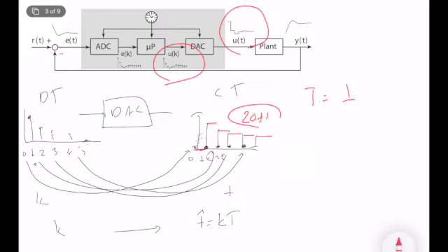Applying zero order hold is cheap and easy, and instead of putting your effort into implementing first order hold or other kinds of hold operators, you just try to increase your sampling rate, which is much better than approximating this function a little bit better to reflect the continuous time action. Okay, so this is the basic idea of the zero order hold operator.